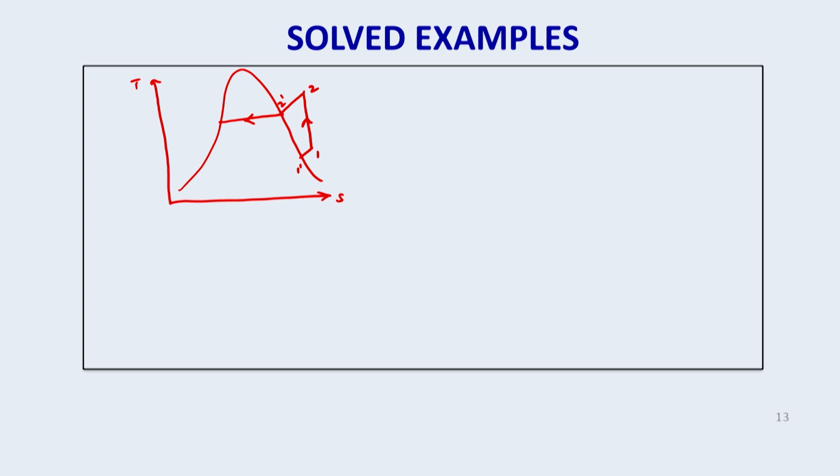And first let me draw without subcooling. So this will be a line perpendicular to the y-axis. So this is process 3 to 4 without subcooling. 1 to 2 is isentropic compression, work of compression. This is heat rejection process, QC.